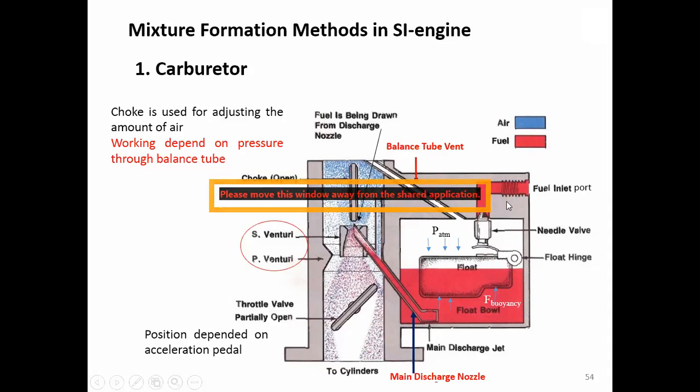Right? Because when the fuel flows in, since it is a liquid, it has a buoyancy force. This buoyancy force will push the float up. When the fuel is at a certain level, the float will push the needle valve here to close, so no more fuel flows in. Right? Above the float, inside the chamber where there is no fuel, the pressure is